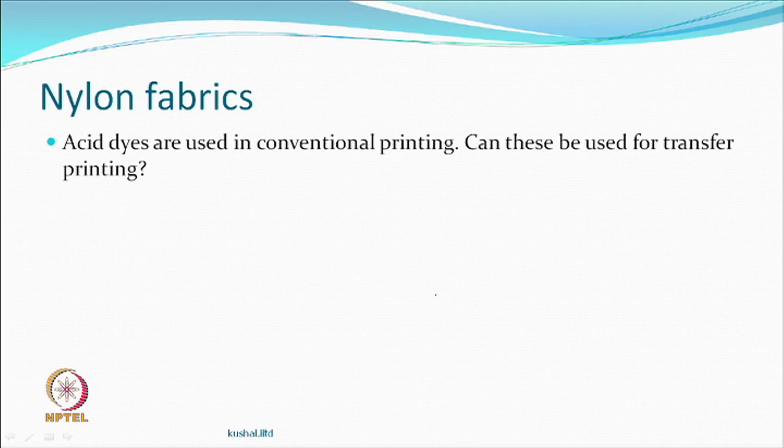So, can we do the transfer printing on nylon? Yes, we can do, right. In conventional printing you like to use acid dyes, right. Can these be used for transfer printing? At the moment we are talking about sublimation transfer. Can they be used? They cannot be used because they are ionic. We said this is something which should not be there, there is no sublimation that will take place.